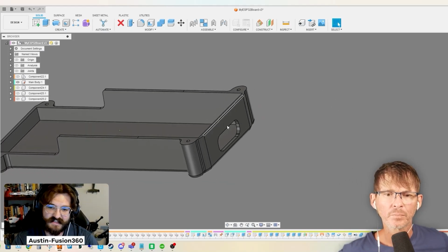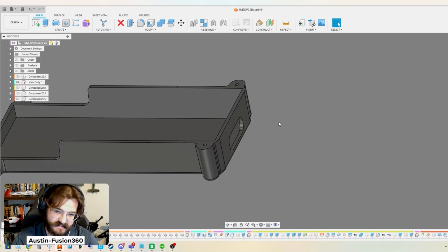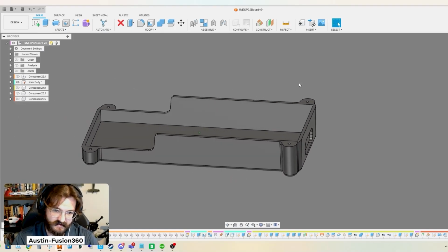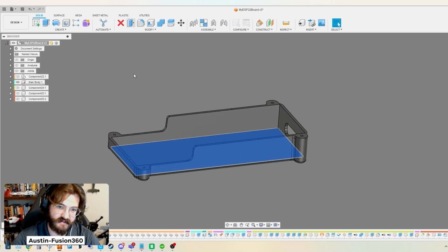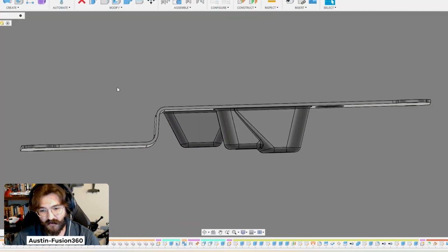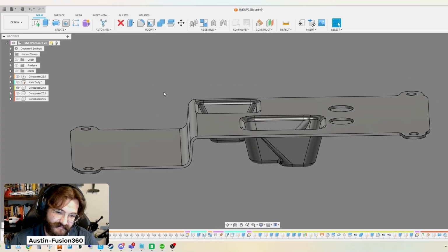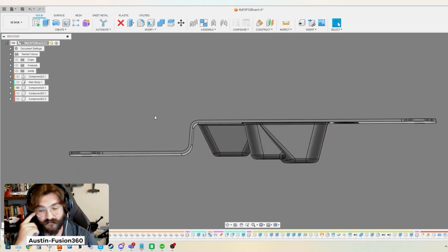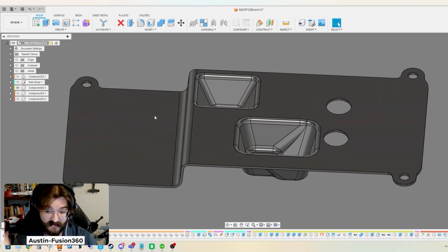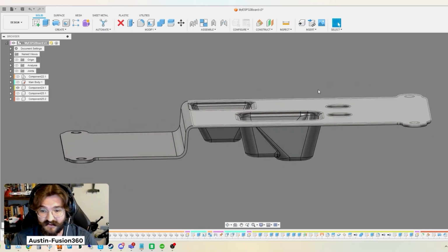Okay. And then there would just have to be a separate piece that's a plug that's fitted in here for the opening. So it'd all get molded together. This plug there would then be removed, and then this part of it would lift up and you would have your part. This is abnormally thin. I shouldn't have gone this thin. The thicken tool was kind of being a bear, so I stuck with currently 0.5 millimeter. It's 0.5 millimeter all around. So this would definitely be really flimsy.